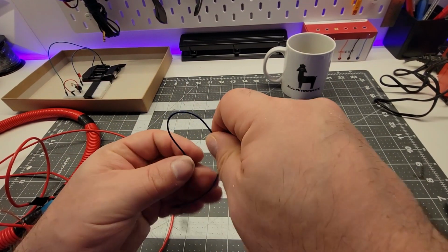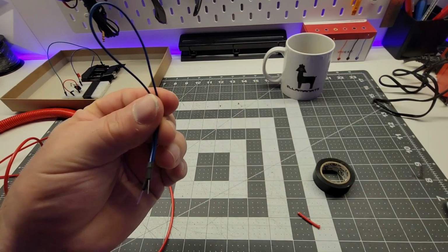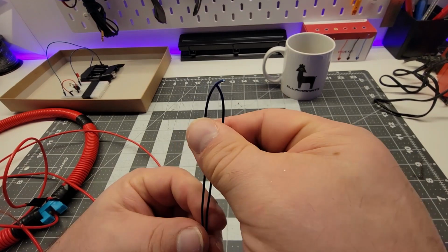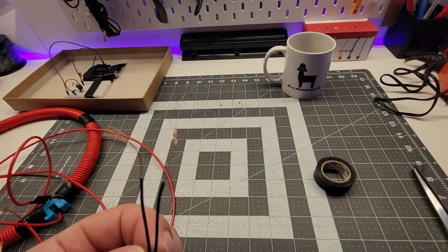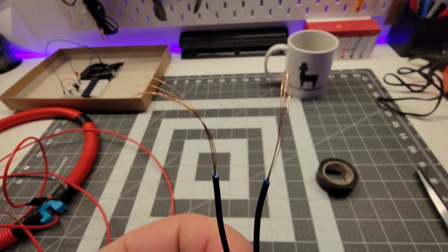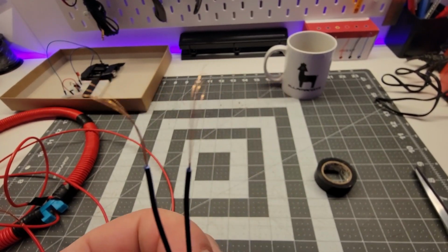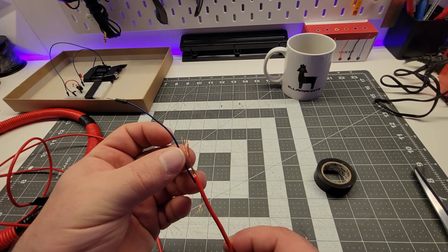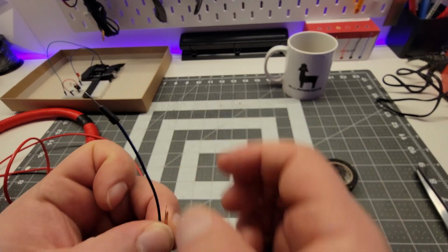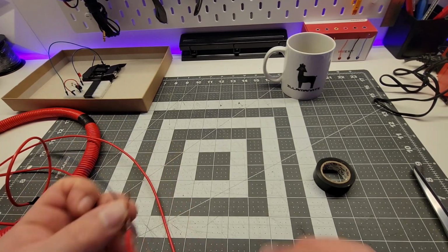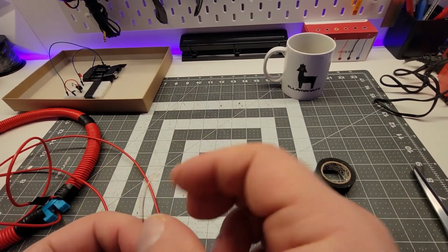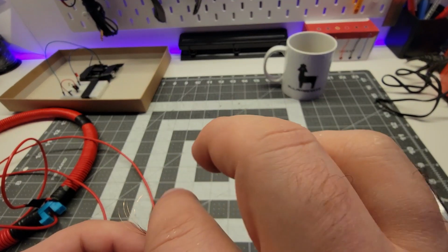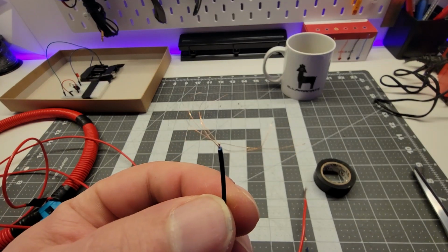We're going to do something roughly similar with this jumper cable, cut it right in the middle, and we're going to strip these two ends as well. And when we're done, we have our stripped ends. And the point of this is to take the end of the lead and splice it on with one of these jumper cables so you can plug it into the board. To make that splice, you take your copper and pull half of it to one side and half of it to the other, just like that.